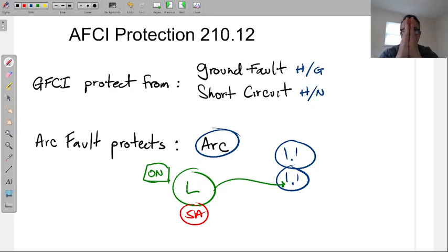So as you try to pull those two apart, the current is like, hey, I was just over there. That was my route. I love that route. I want to, and eventually there isn't enough voltage pushing this current that it stops. The further apart you get, the arcing goes away. Now, higher voltage, you got 1,000,000 volts, then you gotta really pull apart, because that's a lot of voltage. It is going to arc over. So when people are unplugging, that's what it's for.